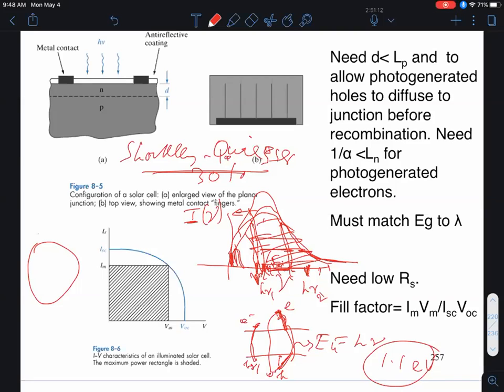and the sun, and it's covered by this atmosphere, suppose I'm at this location over here in Austin, okay, where the sun is shining head on at midday, I get a higher intensity than early in the morning, where the sun has to pass through a larger portion of the atmosphere, or in the evening, right? So all of this is captured in solar cell physics in terms of defining the intensity as so-called air mass zero. Air mass zero is the highest possible intensity that I can get without any atmosphere at all.